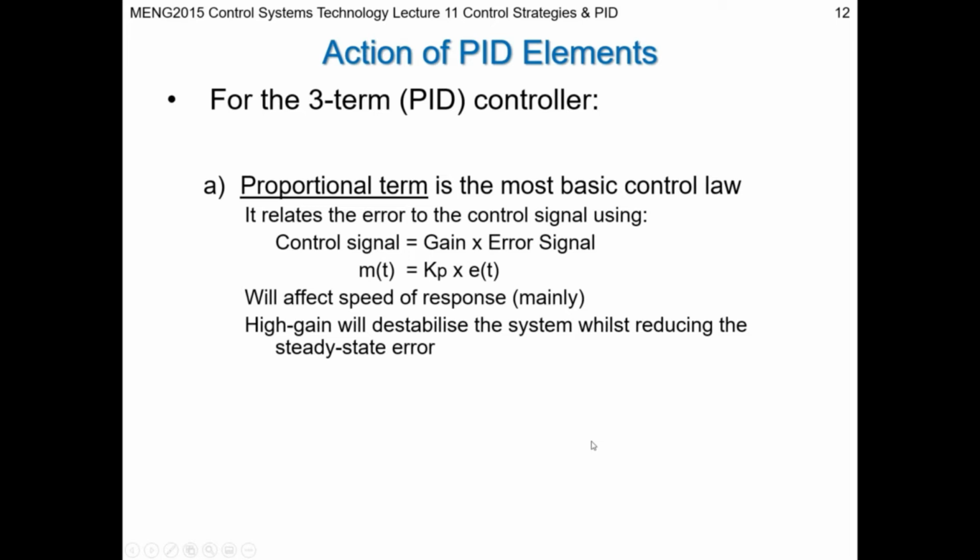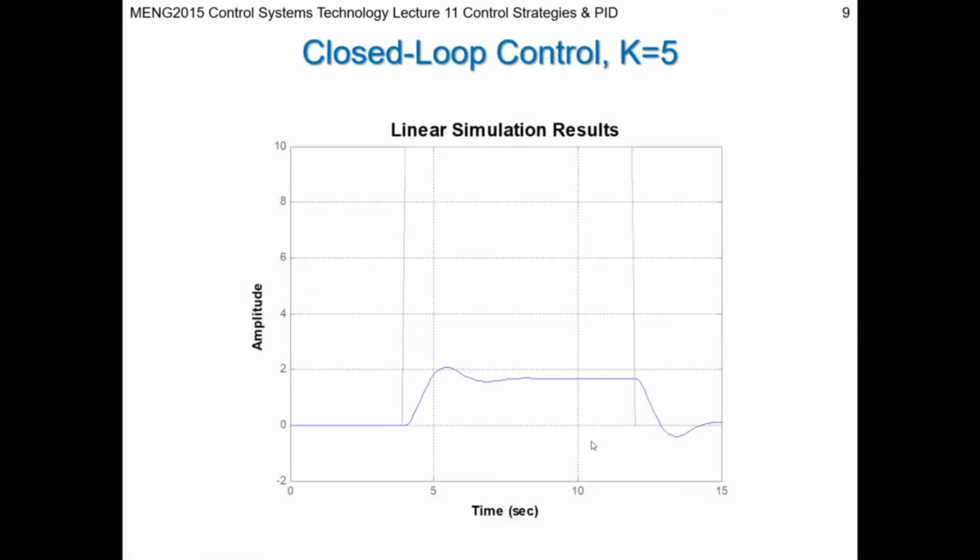So if I go back again to this slide, you can see here, as we get the closed loop system and then increase gain, we've reduced the error that's affected by that disturbance. So that's what the higher gain is doing, but we're also increasing relative instability. So you can see the amount of overshoot here.